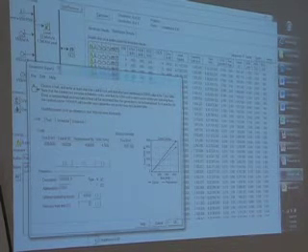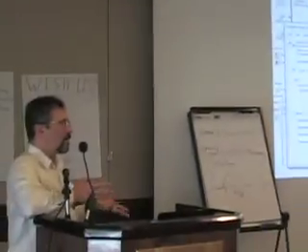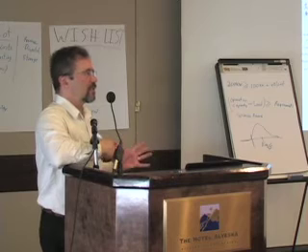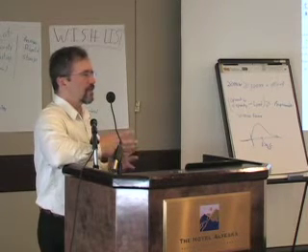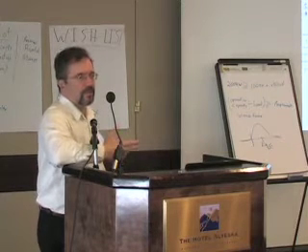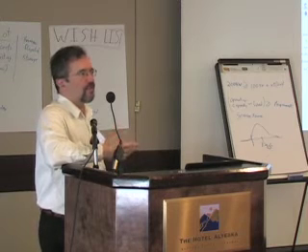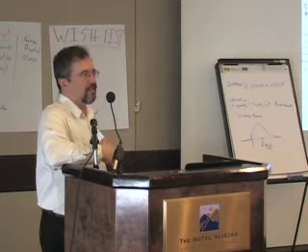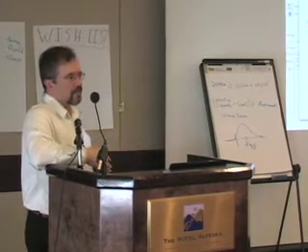And the reason I don't like it is because we've gone back and forth on how we deal with excess energy in the renewable fraction. There's one school of thought that says excess energy is always the renewables. Diesel wouldn't have excess energy, so we shouldn't give the renewables credit for any excess energy. We should subtract all the excess energy from the renewable output and then calculate renewable fraction.